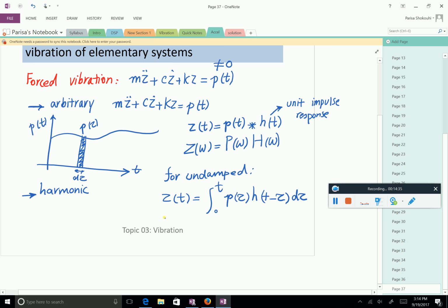It's a nice technology. But anyway, for the undamped case, we can give a face to this impulse response function, which looks like this. This is easy to see because 1 over m would be like a velocity per unit impulse. And it is like velocity over omega times sine. This is really the impulse response of an undamped system, conceptually.